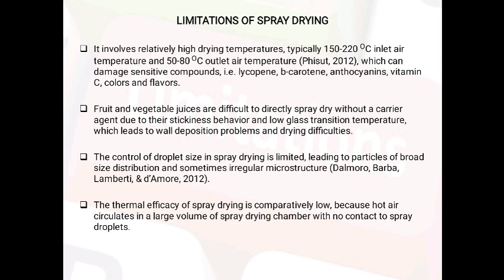Limitations of spray drying. It involves relatively high drying temperatures, typically 150 to 220 degrees Celsius inlet air temperature and 50 to 80 degrees Celsius outlet air temperature, as suggested by Fellows in 2012, which can damage sensitive compounds, that is lycopene, beta-carotene, anthocyanins, vitamin C, colors and flavors.